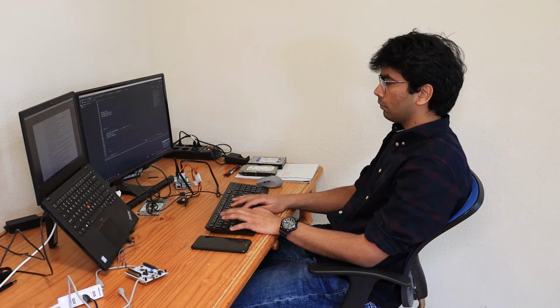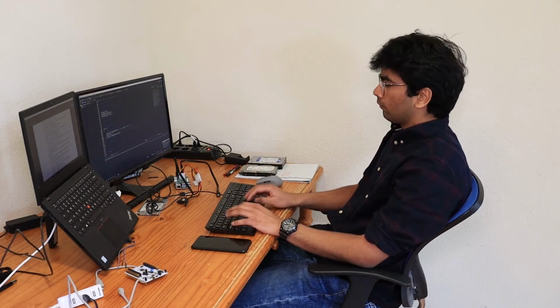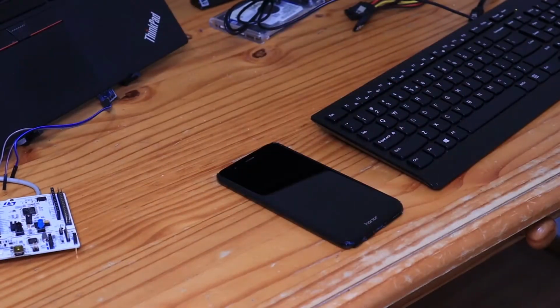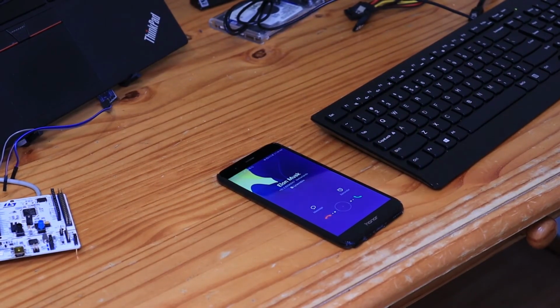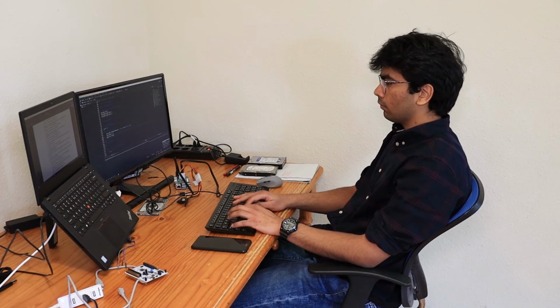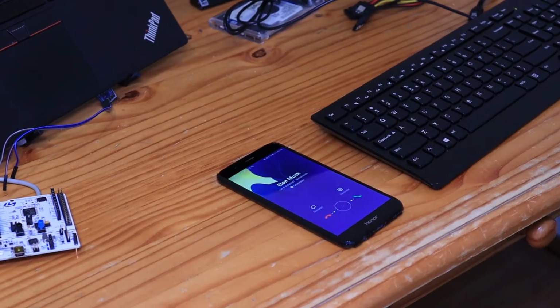A real life interrupt scenario may look like this. You are working on your computer, doing some next level work, and then you get a call, a rather important one that needs to be answered. So you answer it, and then you get back to work. So the part where you are working on your computer is just a CPU processing the code in the while(1) of your main function. The phone call is the interrupt.